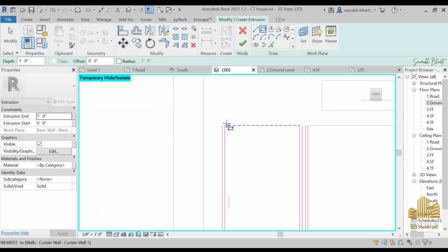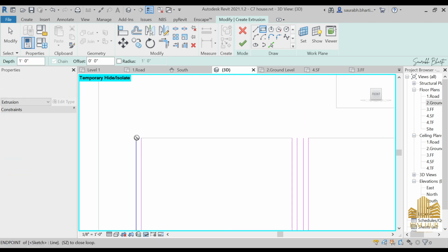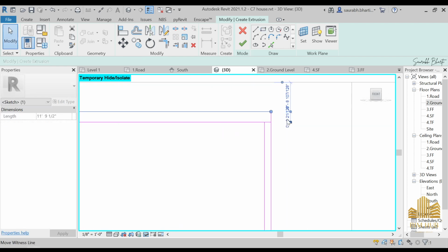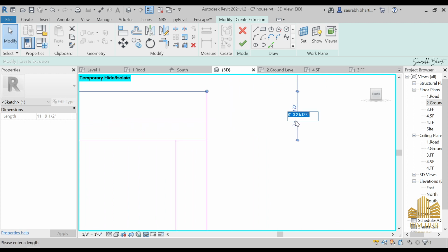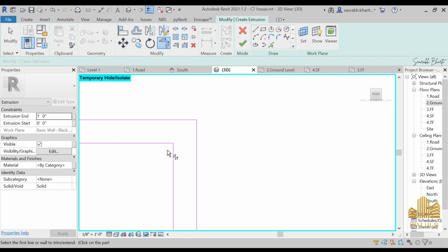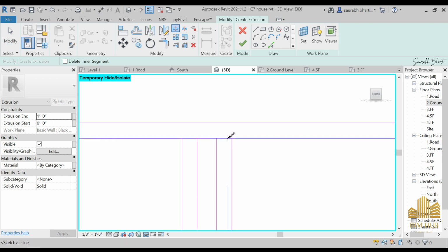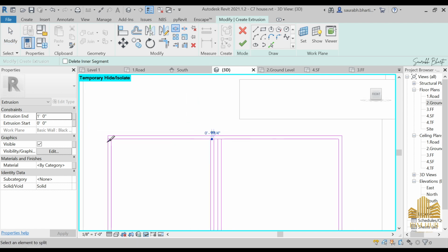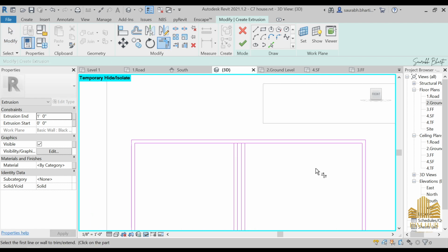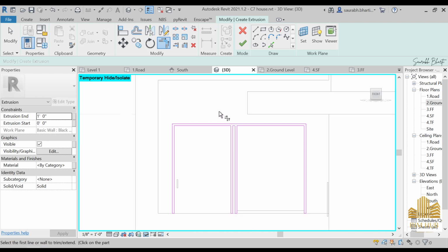Go to rectangle, give it a size of 2 inches again, trim it from here to here. Okay, and here we need to split it first. So SL is the split shortcut, split from the middle and split. Okay, we don't need to split it from here, so just trim it, then trim this part, trim this part, trim this part and trim this part. Done.